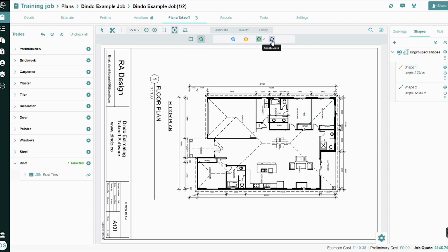That's fine. The difference this time is it's a roof tile, so there's an angle on this area that we want to do, okay? It's not a perfectly flat thing that we're doing, so we need to be able to adjust for that. You're looking straight down at the plan. You can't draw vertical area, you can't draw that height. Volumes, you can't draw the depth, and angles you can't draw. So you have to be able to input that information, which you can do with this little cogwheel here.